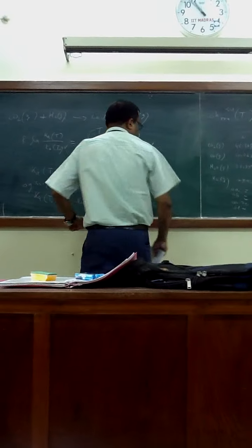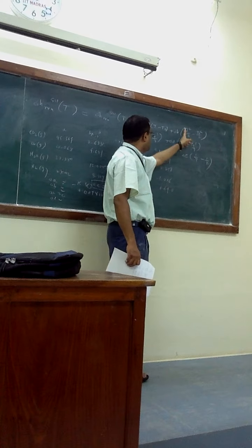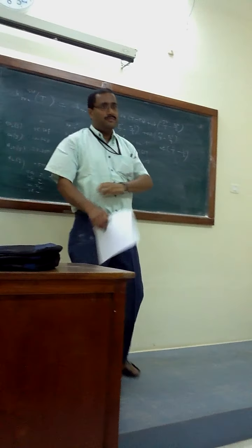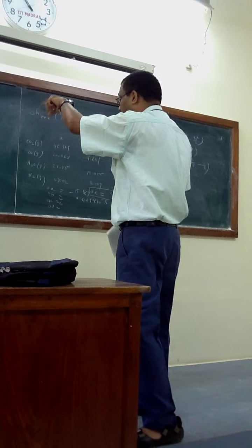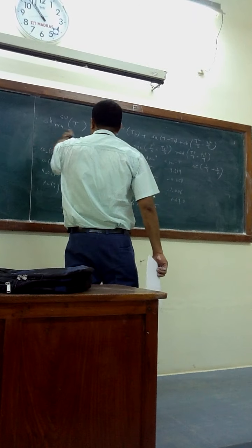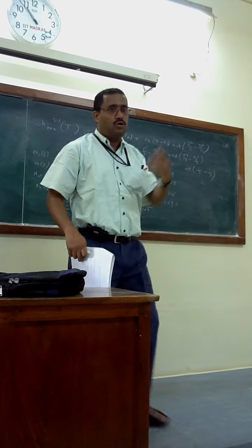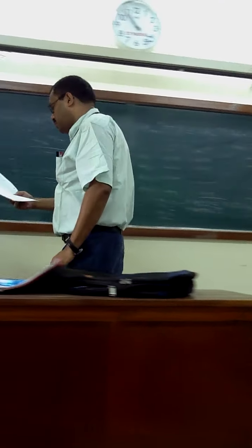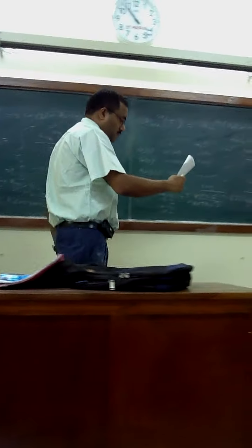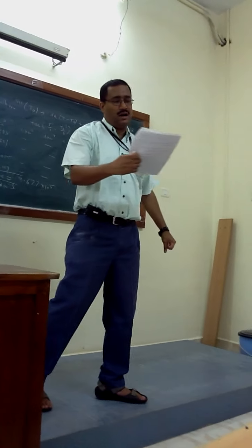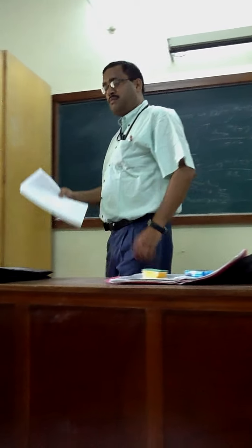Okay, next step: this part is actually done. So all these calculations we have got, and T is known, T0 is known, so you can get this part happily. T0 is known, so we have to integrate. We cannot put T here. It's a function of temperature. And delta H reaction at T0 is obtained with the data already. How much is delta H reaction at T0? How much you got?